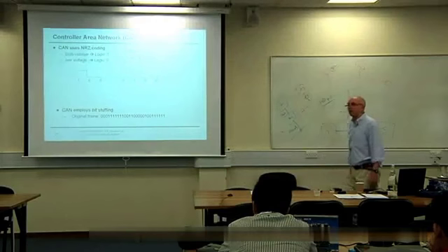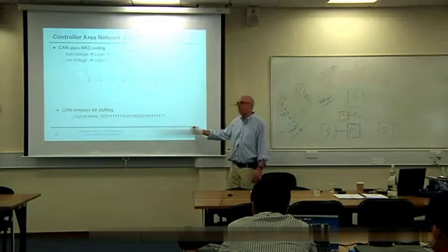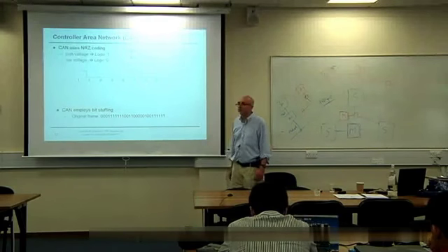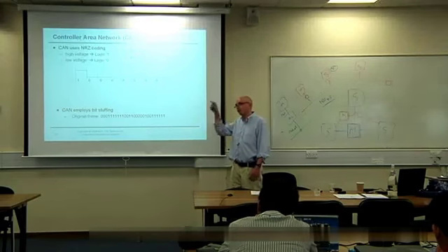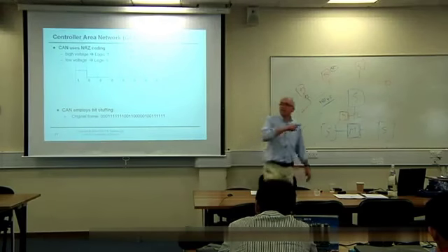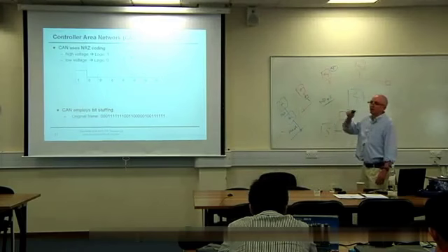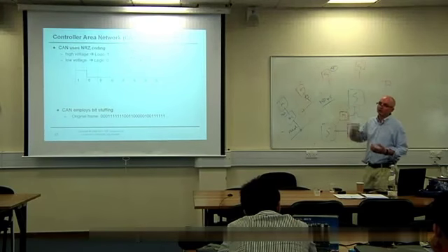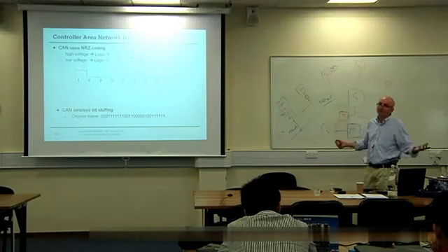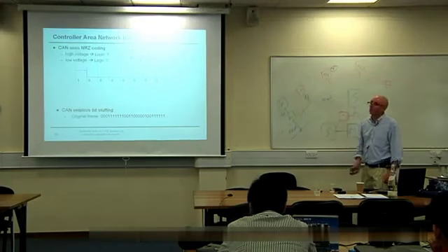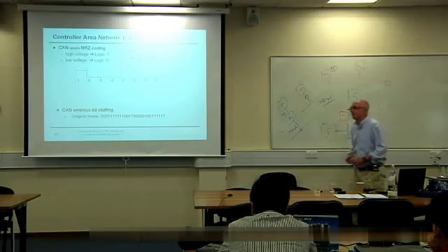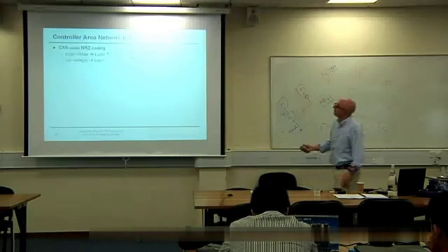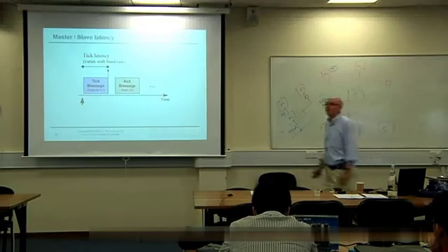That makes sense. So to do that, what the protocol does is, if it's sent 5 zeros or 5 ones, it artificially introduces a stuff bit. So it basically, invisible to the user, adds an additional bit to the message and changes the stream from positive to negative. That's fine. Again, why do you care? Synchronization is sorted. Why do I care?